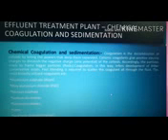The most widely used coagulants are aluminum sulfate, polyaluminum chloride, ferrous sulfate, sodium aluminate, silicon derivatives, lime, and synthetic organic polymers. In the chemical coagulation and sedimentation process, there are coagulation, flocculation, sedimentation, filtration, disinfection, and fluoridation, and seventh is storage. Sedimentation is the physical water treatment process utilizing gravity to remove suspended solids from water.